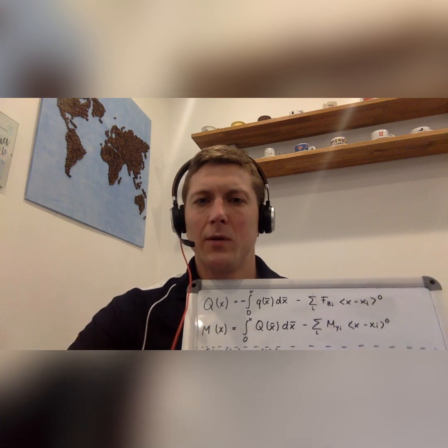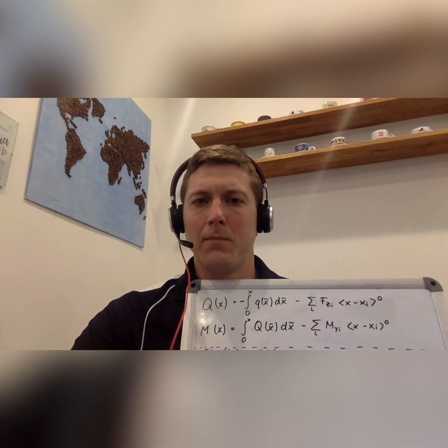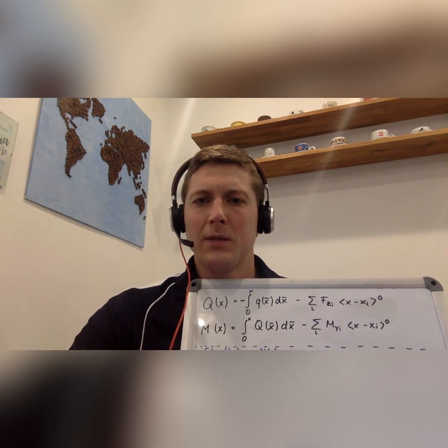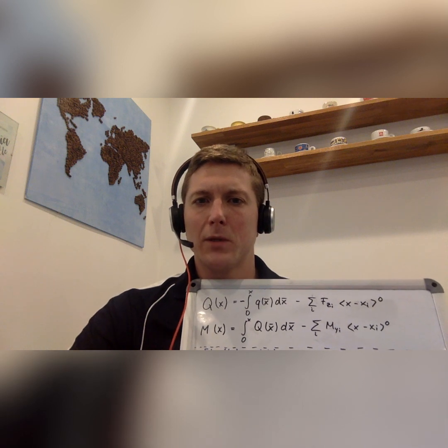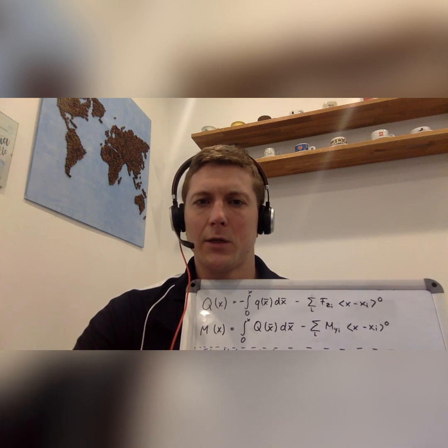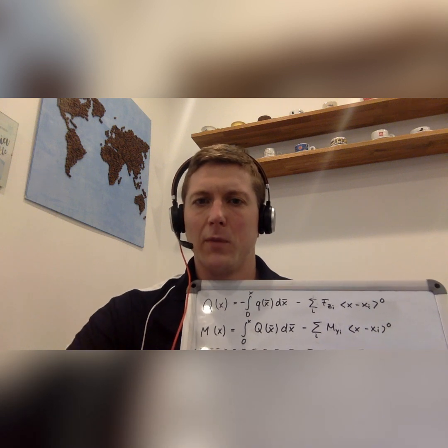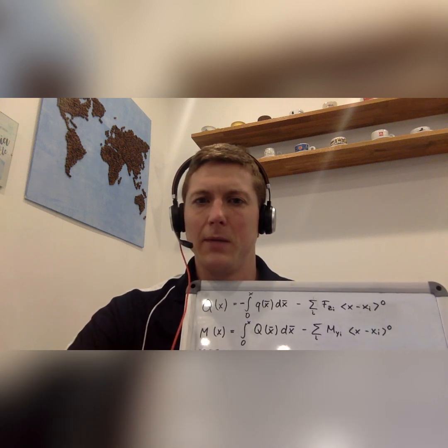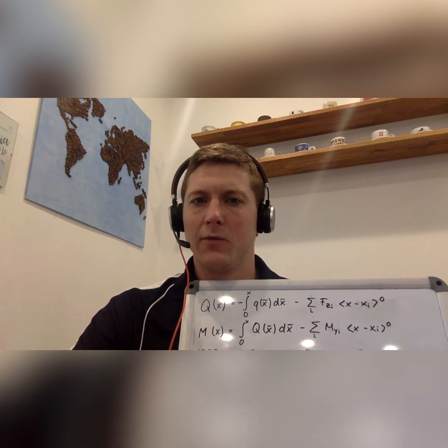But right now we come to our new topic, which is bending of beams, so mechanics of materials. And in this case, there might be systems where you are not able to determine the bearing reactions in advance. So it might be possible that you could just set up for your beam 3 equations: equilibrium in horizontal direction, sum of forces in x direction; equilibrium in z direction, sum of forces in z direction, where you would have the shear forces; and equilibrium of moments with respect to the y-axis, where you would have the bending moments, and of course the influence of the shear forces as well.